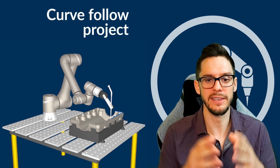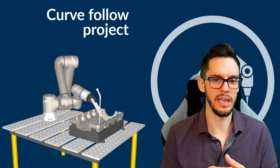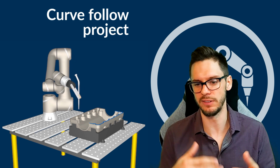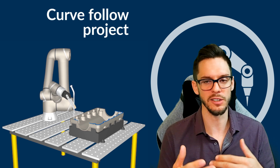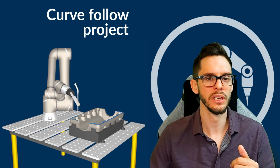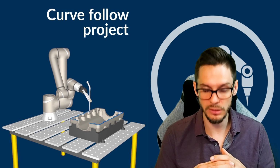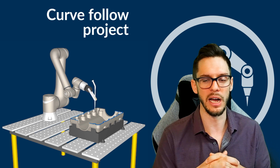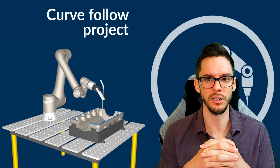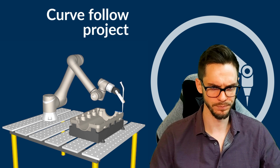There are different ways to generate the path itself. You can extract it directly from the 3D model imported in RoboDK. You can import it from a list of points as a text file or a CSV file. You could have created that list of points manually, or let's say with a custom algorithm that you created. And you can also import it using one of our CAD plugins. So this is a super strong combo, but I'll give you more details on that in a few moments.